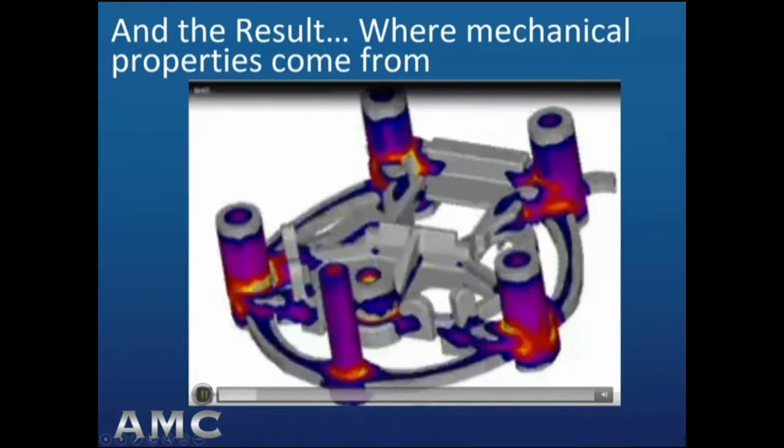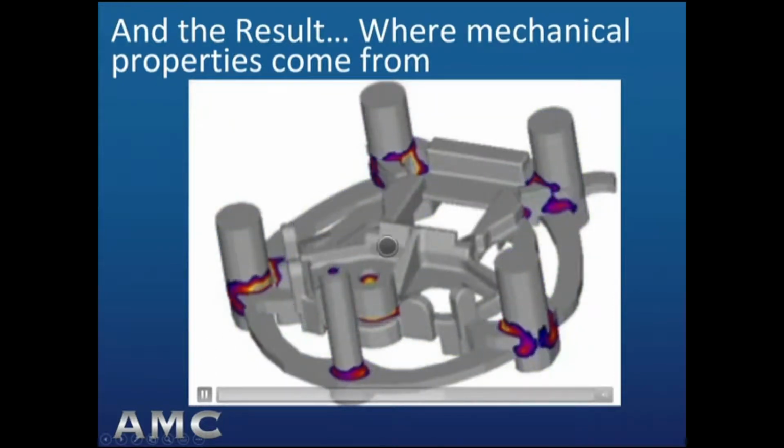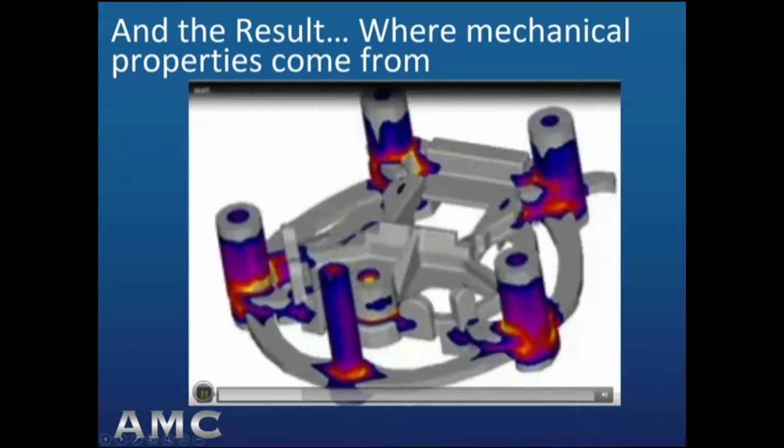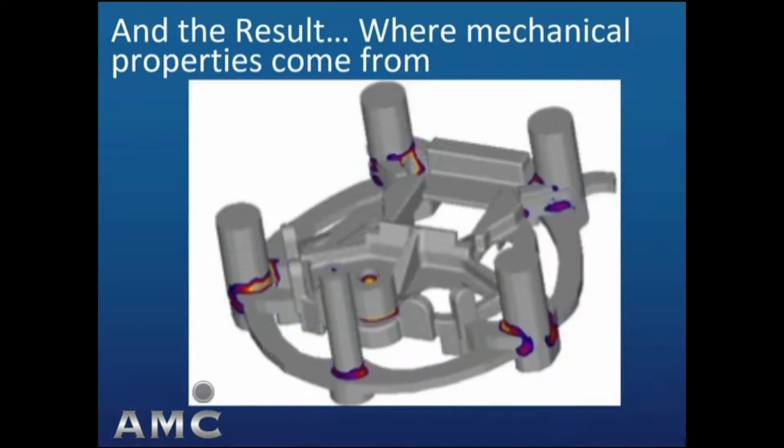And you can see those clear up nicely. That critical fraction solid at that point was great enough that we were able to feed those little blue spots to solidification integrity nicely, and didn't have solidification shrinkage problems that would affect the mechanical properties.